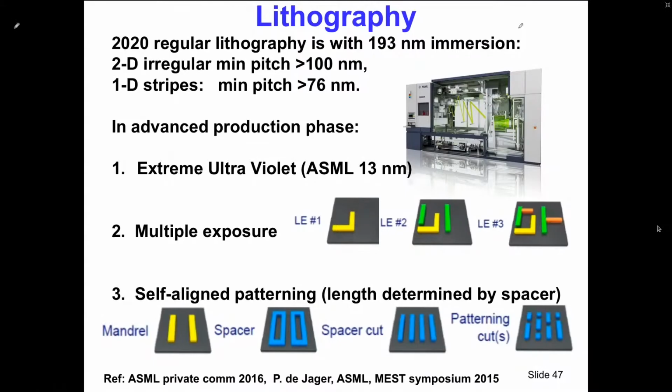If you go into the foundries, you will find massively 193 nanometer light in immersion, with numerical aperture improvement, and that means that for irregular shapes, your pitch must be more than 100 nanometer. And so all these guys that talk about 45 nanometer processes, now forget about it. It's just commercial humbug, yeah. Because in fact, the lithography is always worse than these type of numbers.